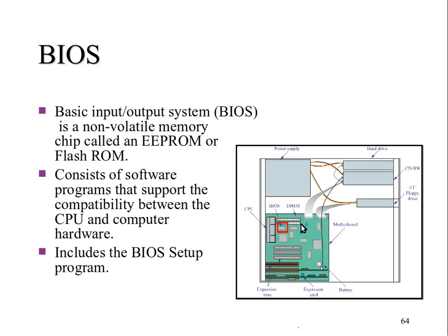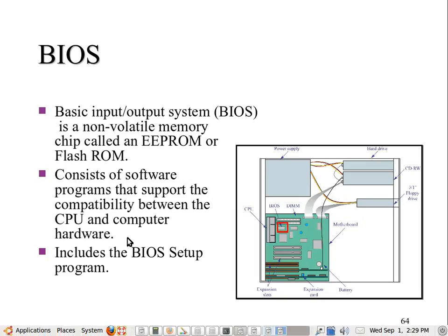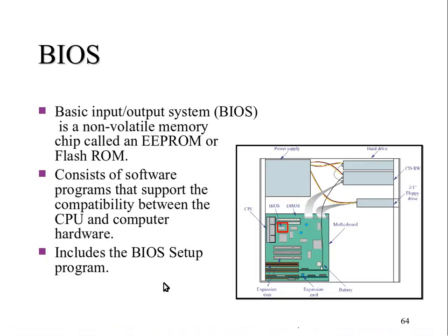Well, it runs the BIOS actually, but the BIOS does the job of communicating with a lot of the hardware in your computer, and it acts as a go-between between the operating system and the hardware and the application programs as well. And it also has what's called a setup program. So sometimes as a service technician we will go into what they call the BIOS setup and we'll make changes to the settings. And it can also help us troubleshoot things, because one of the things the BIOS does is it does a power on self-test, POST it's often referred to.